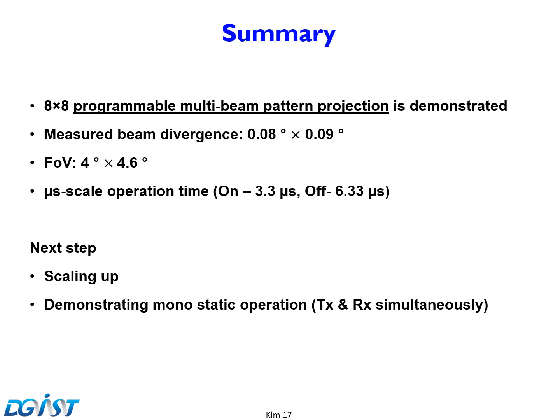In summary, we demonstrated 8x8 programmable multi-beam pattern projection based on multicast silicon photonic MEMS switches. MEMS switches give us relatively low power consumption and fast operation speed. The divergence of the emitted beam is 0.08 by 0.09 degrees. The field of view of our device is 4 by 4.6 degrees. Now we are trying to scale up our device and demonstrate monostatic operation.